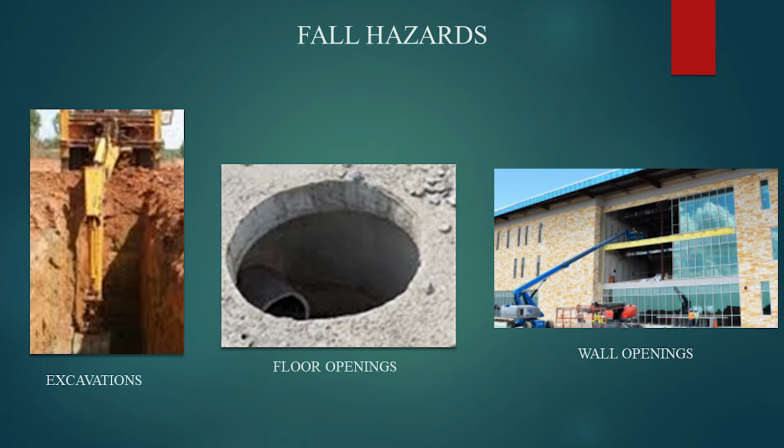An excavation is any man-made cut, cavity, trench, or depression in the Earth's surface formed by earth removal. Excavations are hazards when they are 6 feet or more in depth and not protected using a guardrail system, fence, barricade, or cover. A floor opening is any opening measuring 12 inches or more in its least dimension and 4 feet deep in any floor, platform, pavement, or yard through which persons may fall. Floor openings can be any walking or working surface with holes that measure 2 inches in diameter and more than 4 feet above lower levels.